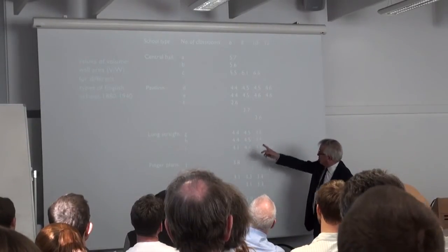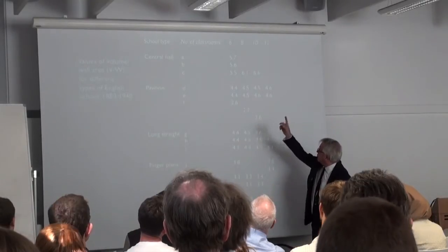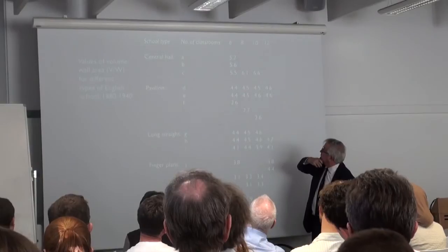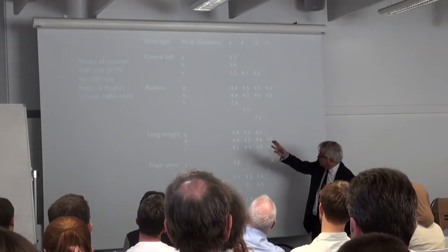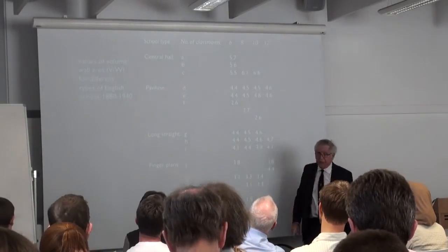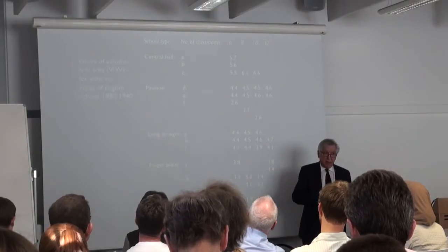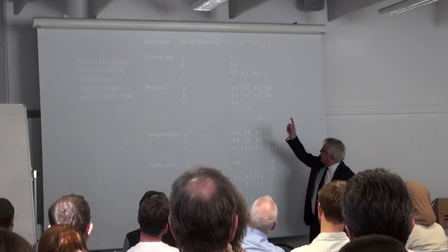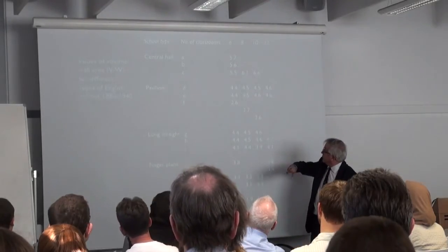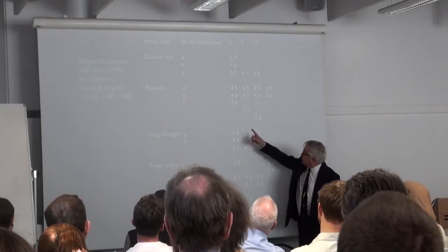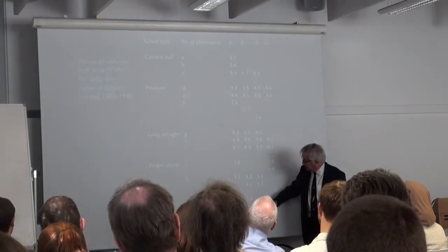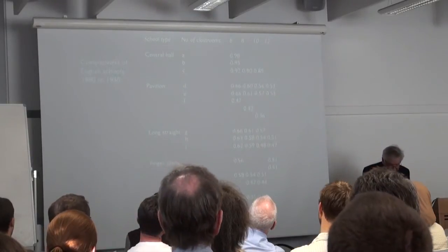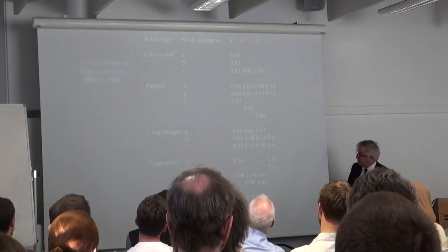And look down this column of 6 classroom schools, so they're directly comparable. You'll see that at the beginning, this measure of volume to wall area is about 6. So that's half plan depth. Actually, we've got to allow a bit more because these are squarish plans, so they're 15, 16 meters deep here. Going down continuously through this period, it gets to about 2 with the open air schools. And this is this measure of compactness, which I described at the beginning.